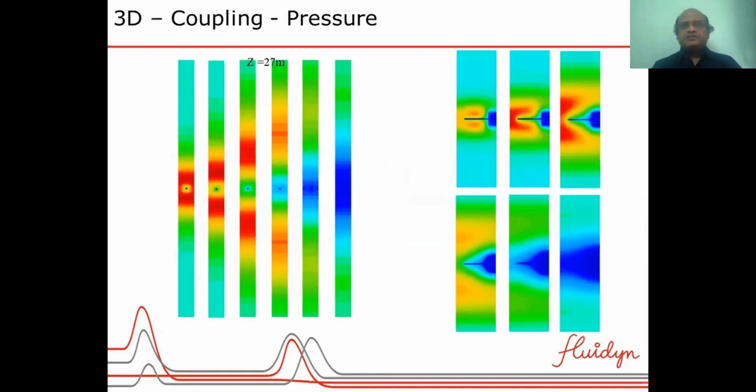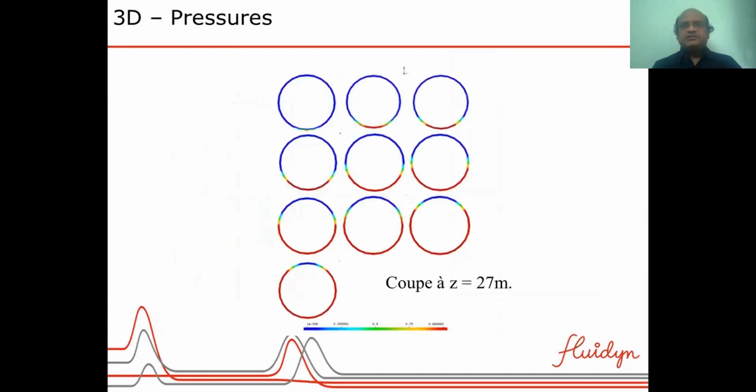So various quantities are assigned. Also, we estimate how much seepage occurs into the gaps between the steel protection and the rock. And the red color here shows the development or filling of the gaps with water. We find that in about 100 years, half of the gap is filled with water.